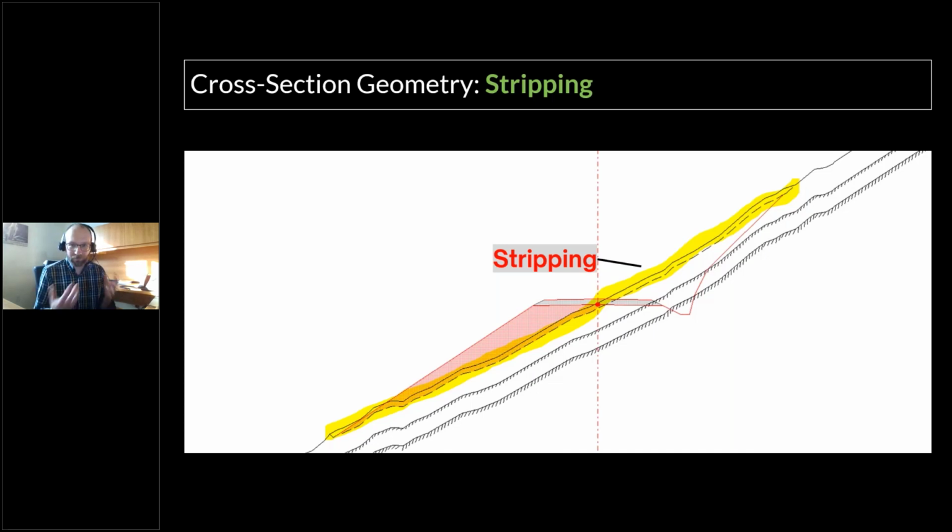So to get around that, usually we'll remove a weak soil layer. And oftentimes in new construction, that weak soil layer is going to be organic soils right on top of your surface. So we'll strip away those organics and make sure we're building on competent, strong material. We do that to help ensure that the fill slope or fill that we build stays there.